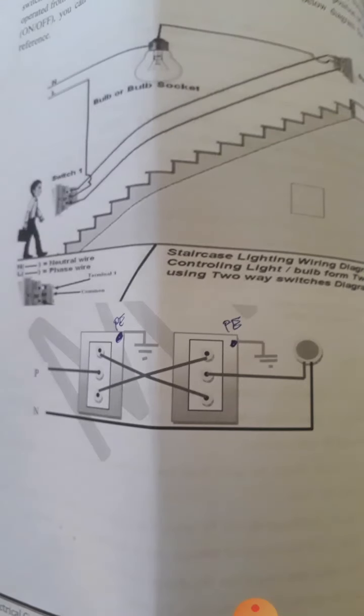wiring diagram, and this is how to connect a two-way switch. You see there is a staircase. When you enter the staircase there is one two-way switch, and after you reach the first floor there is another two-way switch, and the bulb is at the center. So the phase goes from the DB directly to the bulb, and one wire from the bulb returns to the DB to take the neutral directly, and the phase goes directly to the center terminal of the switch downstairs. The bulb has two terminals, one phase terminal and another neutral terminal, and the phase terminal goes to the center terminal of the other switch. The remaining two terminals are balanced across the two switches, so we can give the loop. So this is the diagram of this one.